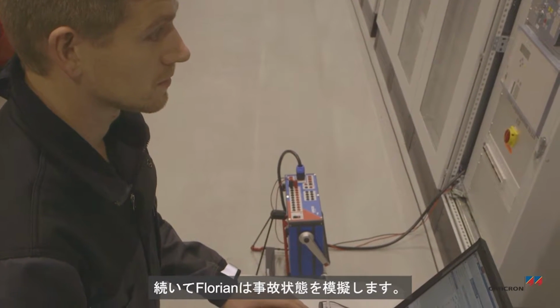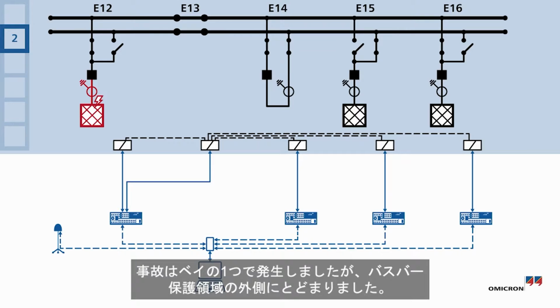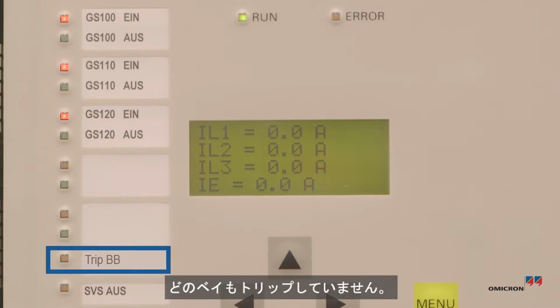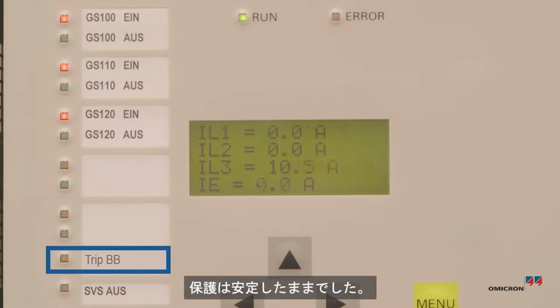Now Florian simulates a fault. Although the fault has taken place in one of the bays, it remained outside of the protected area of the bus bar protection. None of the bays have tripped. The protection remains stable.